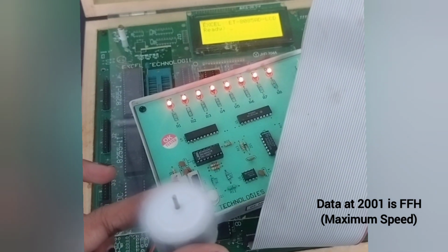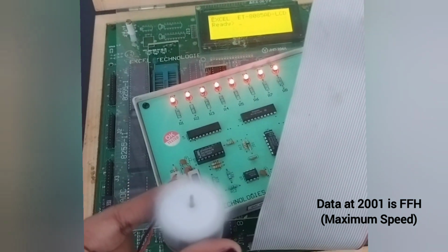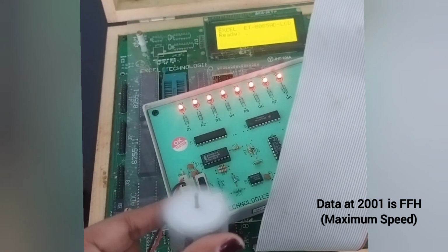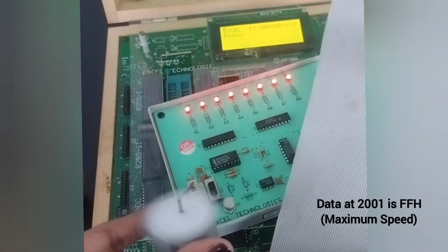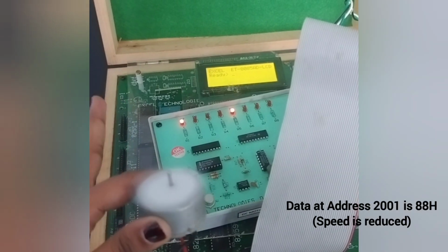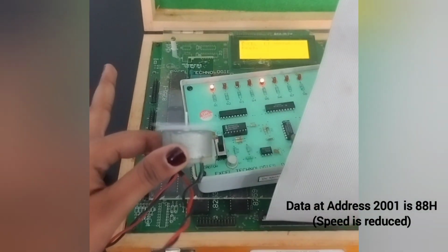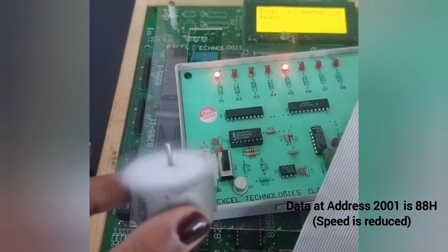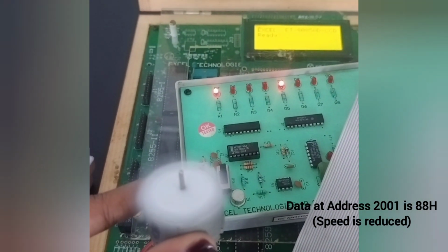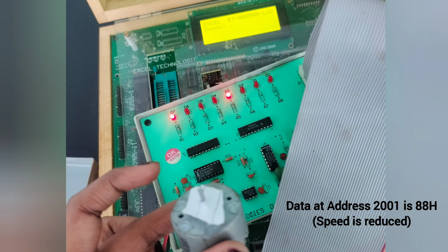For the data FF at 2001, we observe that all LEDs glow and the motor rotates at its maximum speed. When we change the data at address 2001 to 88H, we observe the R1 LED and R5 LED glow and the motor speed reduces.